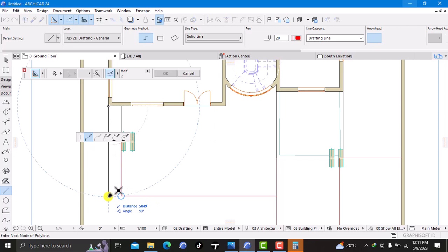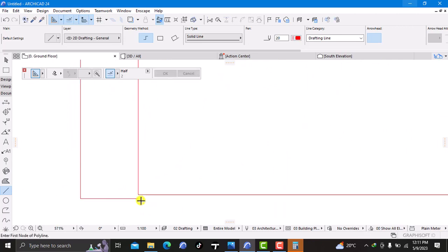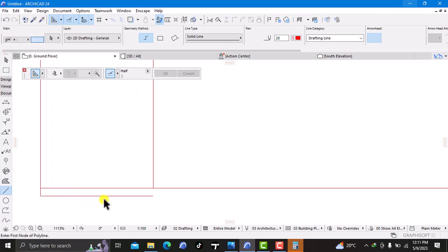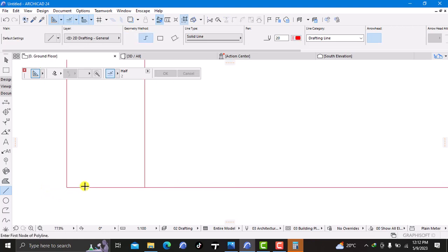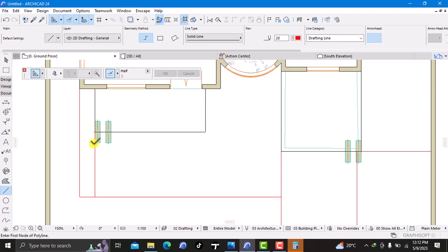So at this point maybe these lines don't make sense to you, but they will really help you a lot when you are doing the road caps and the landscaping of this. Let me suspend the script, and then just drag this to that edge so that I'll have my road cap running from this edge all the way to this edge.